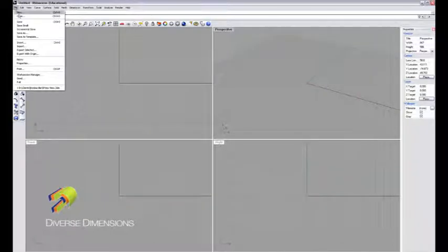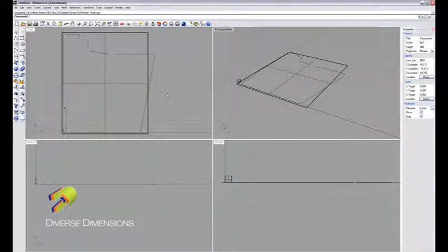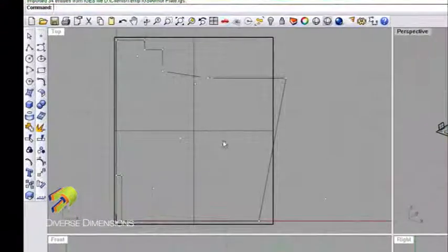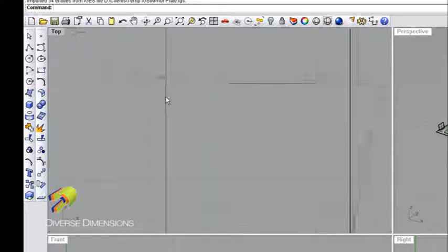I just go ahead and do a file open here. Got IGES here as my selection, the type of file I want to pull. Here's my armor plate. Notice when I pull that content in this top view, look what I get. I've got the outline here and all the points that came out associated with those corners. I've got all the point content that was where the circles were and the plane. Of course, I've got the big flat plane underneath that I used to sketch all of my entities too. But notice I do not have any hole content. So if I zoom in a little bit, I've just got points here. Points where the circles are supposed to be.